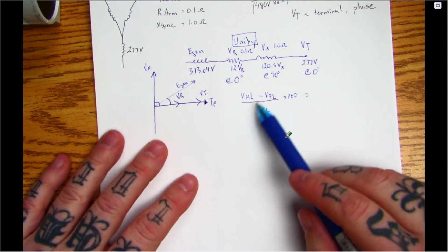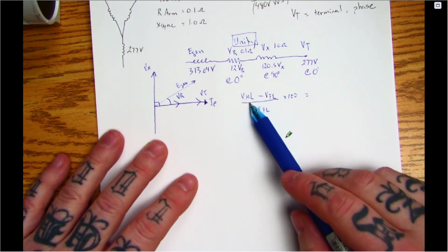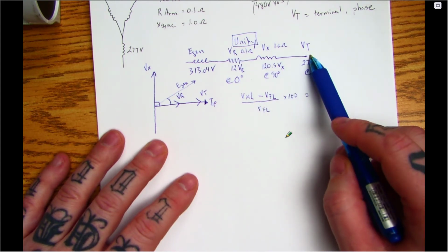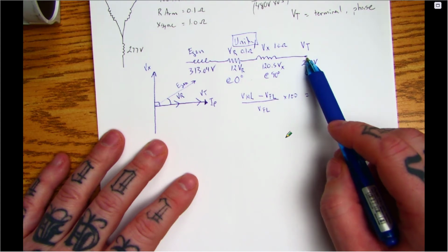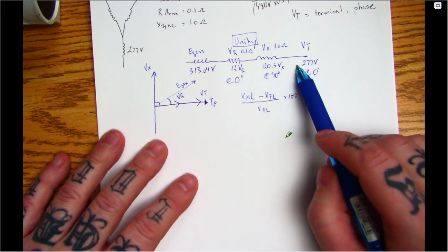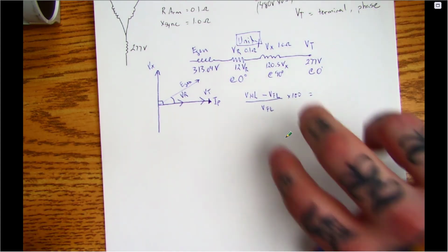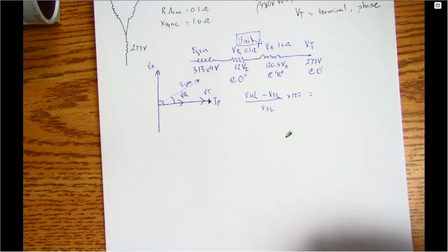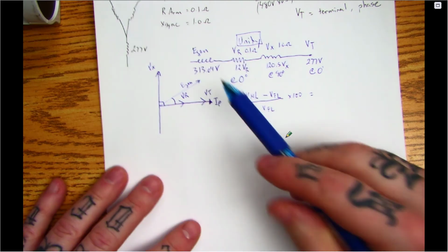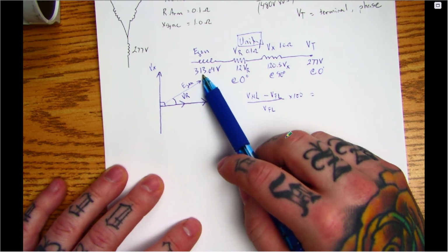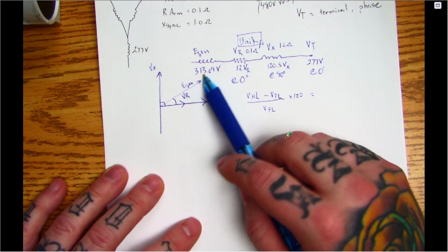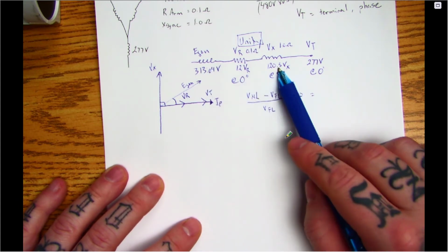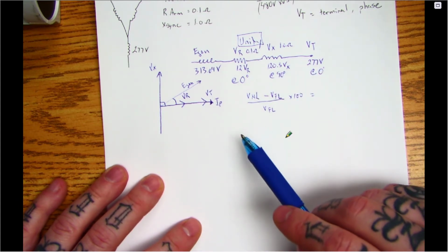Now, what we look at as no load is our E-gen, because we think of it as if I didn't have a load, or say I had this load on and everything was adjusted, I've increased or decreased my field excitation just enough to get this 313 volts, so that I can generate and deal with these volt drops and still have my terminal voltage.